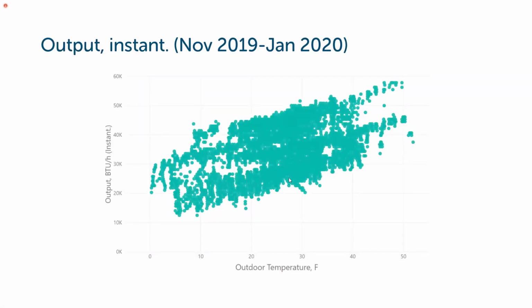And this just shows you similarly what the output of the heating equipment was at the different temperatures. At 0 degrees outside air temperature, you're still getting between 20 and 30,000 BTUs of heat. And I think Brian's design load at minus 11 was 35,000 BTUs, and that's at design temperature. So again, for most of the heating season, his load is probably in the 20,000 BTU range. And you can see that the heat pump is more than providing what the building would need for heating energy during the bulk of the season.